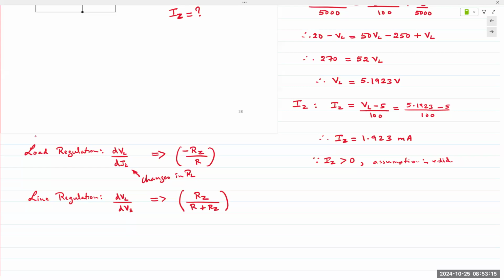The output of the bridge rectifier circuit will now drop to 15 minus 1.2, so about, say, 13.7, 13.8 volts due to the diode voltage drop. We apply a filter capacitor in there. Let's say we have a filter capacitor of 10,000 microfarads, which will result in a peak to peak ripple of 100 millivolts or less. So from 13.8 volts, we now have a flat line of, let's say, 12.5, 12.6 volts with some sort of ripple. And then we give that into a Zener diode.